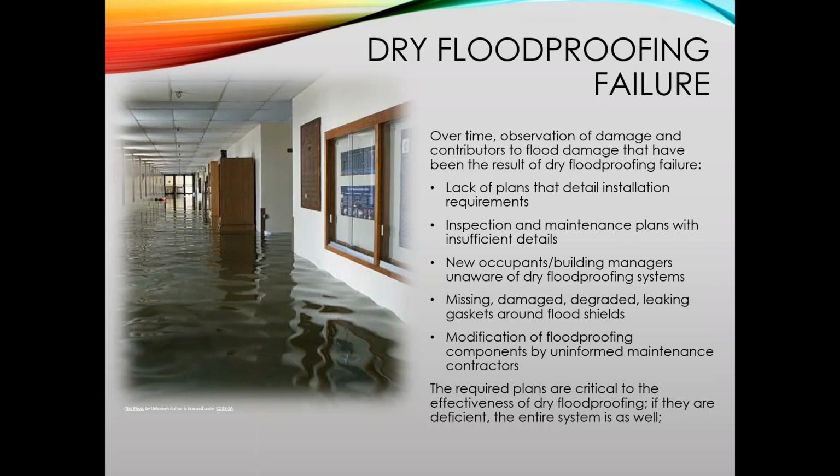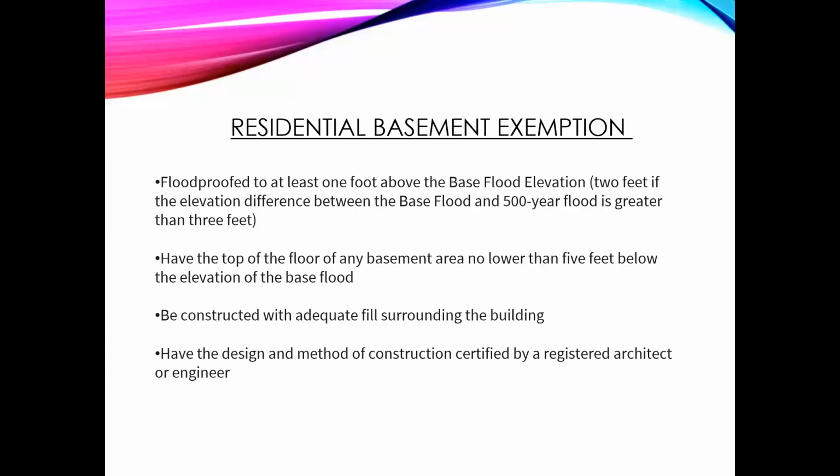And so that's why these plans are a critical component to the effectiveness of a dry floodproofing design, because if they're deficient, then the entire system is going to be deficient. And so that's probably why dry floodproofing is not very common. But again, there is a new dry floodproofing certificate that should be coming out. As I said, if you are going to dry floodproof, then they have to have this certificate.